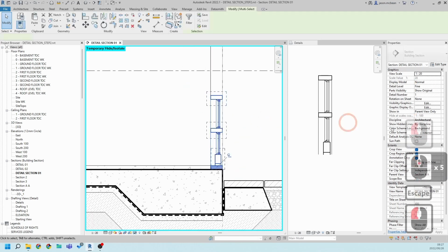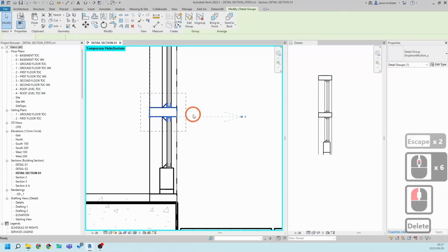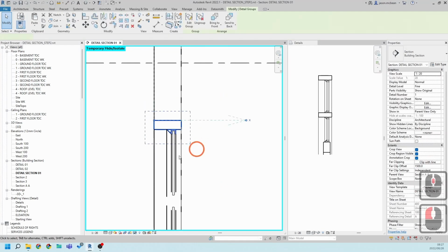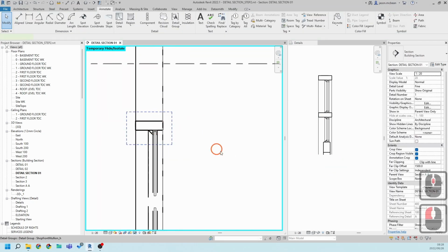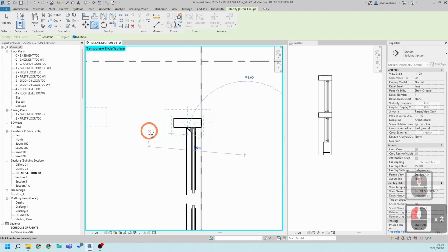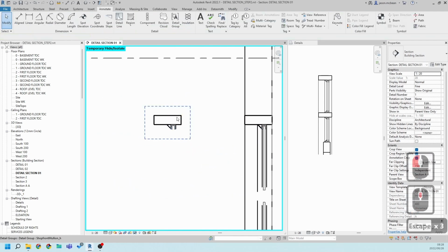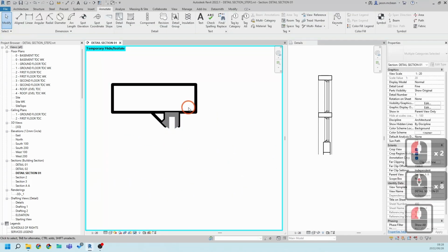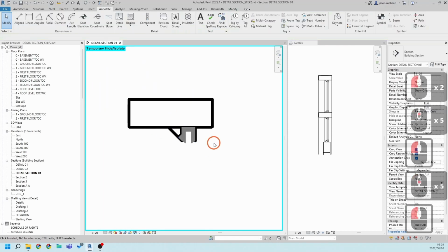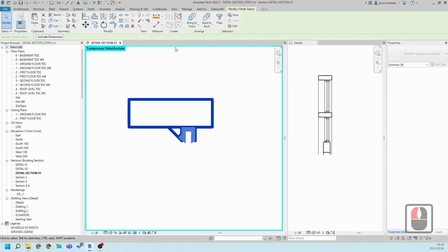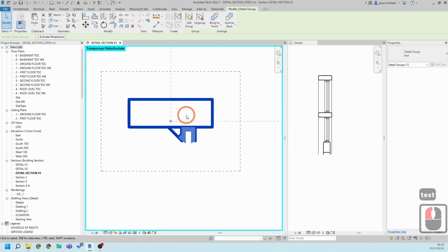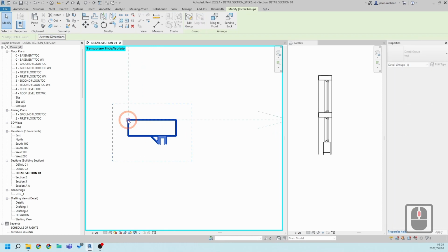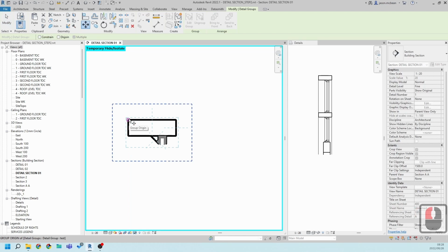So copy this to the side. Just remember you've got the copy here, and these are blocks. Just remember in my previous video, I showed you how to make groups. In essence, all that these are, let me just copy it to one side, is a series of drafted lines and fills that I've put together. All I've done is select everything and make a group. Give it a name. Just remember, you can move this point, so it gives you a snapping point. If I go move, it gives me a nice snap, an origin.